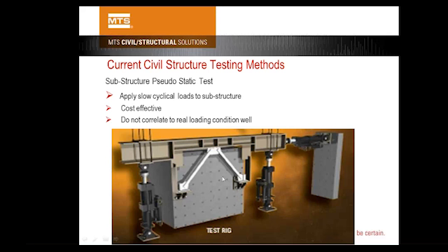But the disadvantage is that the loading is not realistic. You use three cycles of sine wave, then change to another level, another three cycles of sine wave or triangular wave. No earthquake is like that, so the loading is not realistic. That's the disadvantage of this kind of test.